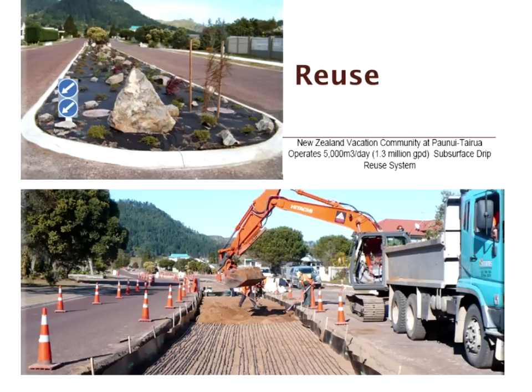And you have to design it and know your soils very, very well and know your plants very, very well. Because there's got to be cooperative work between the landscape architect and the engineer. Landscape architects are not skilled in soil science for sewage disposal. They may know something about soils for growing plants, but very few of them know anything about soils for sewage disposal. And you're going to have some percolation down. You're going to vary your depth of burial and your spacing of burial according to the needs of the plants. So it becomes very much a cooperative engineering job.